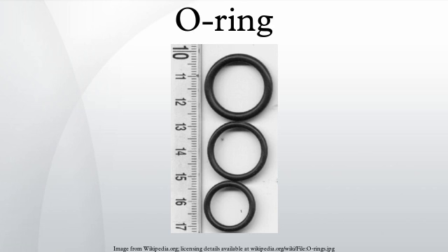Using conductive carbon black or other fillers can exhibit the useful properties of conductive rubber, namely preventing electrical arcing, static sparks, and the overall buildup of charge within rubber that may cause it to behave like a capacitor. By dissipating these charges, these materials, which include doped carbon black and rubber with metal filling additives, reduce the risk of ignition, which can be useful for fuel lines.